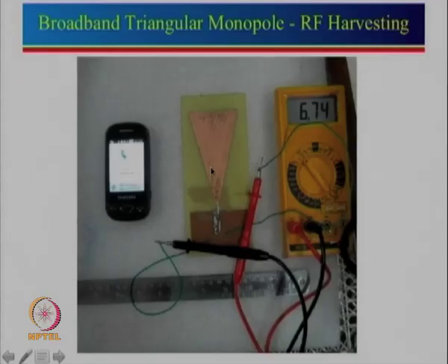Now this configuration we have recently used for an ultra broadband microstrip antenna configuration. What we did is we put a ground plane behind this. So by putting a ground plane, this is one ground plane. Now think about another ground plane, or in fact let me call that another metallic reflector, placed behind this here. Now the general concept is that you put that metallic reflector behind at a spacing of lambda by 4, but I would just like to mention that it should be a lambda by 4 spacing at the maximum